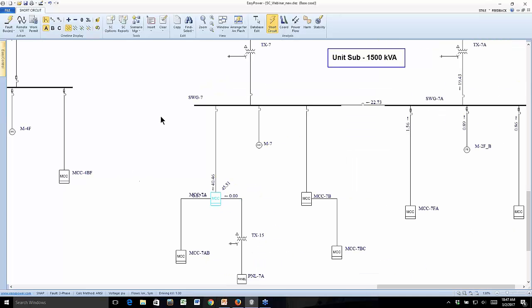One last thing we'll go over here is a feature we added. We had customers request the ability to display short circuit currents and arc flash results in their panel schedules when they print the panel schedules and the MCC schedules. So we've added this capability called fault and store, and we kind of hide it, but it's here. So we go to fault buses. There's a little triangle there. You can drop this down. There's a few options, and down under the advanced, there's a fault and store symmetrical kA and fault and store arc flash.